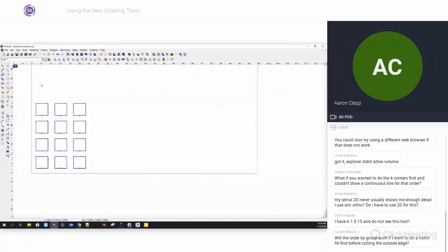So it won't let you do that, mainly because if we were wanting to do that, I would probably use the manual ordering. So I could use the set toolpath order in that case. And what I would do is set this one to number 1, and then set. Oops, I gotta hit enter there. You know what? It would be easier if I just went manual. 1, 4, 2, 3, 4, and then I did this. That would probably be a better way to do that specific one.